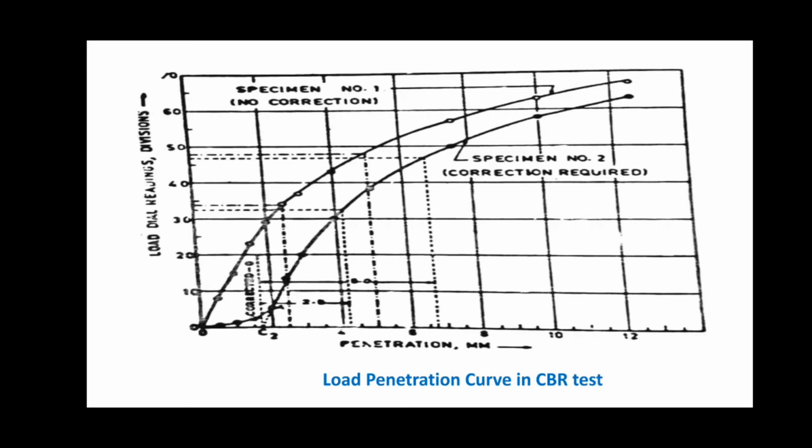As you know, the design curves correlate the CBR value with the total pavement thickness cover, which was developed by the California State Highway Department for the wheel loads of 3175 kg and 5443 kg, representing light and heavy traffic. Later, the design curve for a 4082 kg wheel load was also obtained by interpolation for medium traffic.